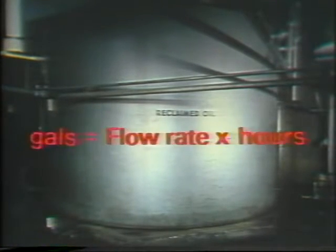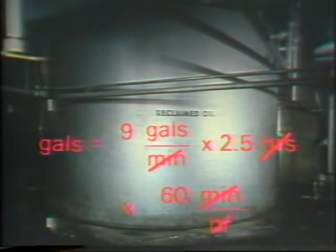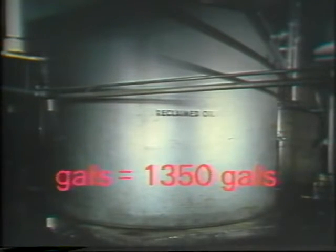Let's say that you've been transferring oil to this tank for 2.5 hours at a rate of 9 gallons per minute. How much fluid has been transferred? To find the amount of oil that has been pumped, we multiply flow rate by the hours we've been pumping. That's 9 gallons per minute times 2.5 hours. To convert hours to minutes, we also need to multiply everything by the conversion factor, 60 minutes per hour. The hours cancel, the minutes cancel, and multiplying everything out, we find that 1,350 gallons have been pumped into the tank.